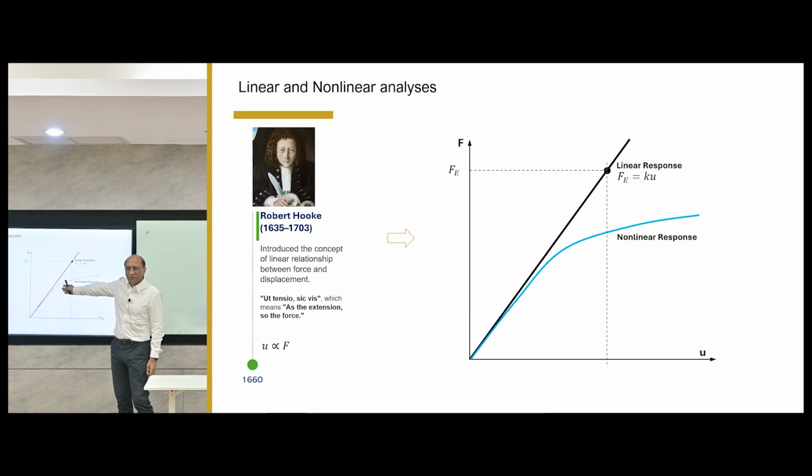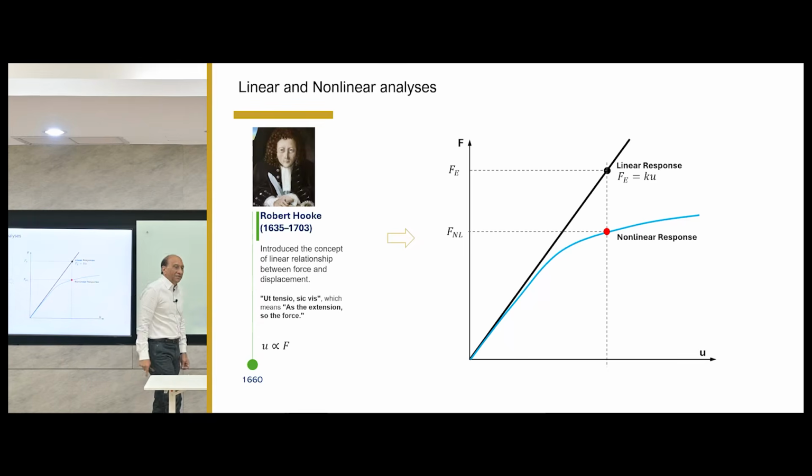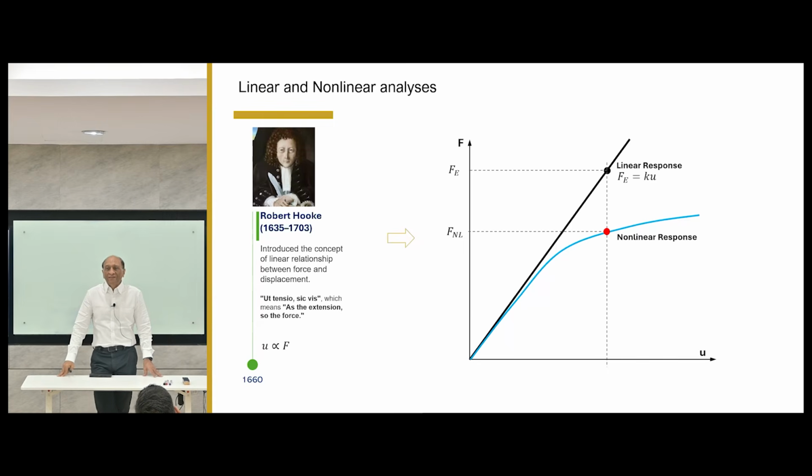Especially in earthquakes, the damage was quite obvious, right? So they found that, okay, nonlinear: for a given displacement, because displacement is the primary variable, you remember. Force is calculated from displacement, velocity, acceleration, or displacement based. So for a given displacement, we have the nonlinear force here and the linear force over there. It's quite clear that the linear equation is highly overestimating the force the structure can take. The structure cannot take that much force at that displacement. It has already broken down, already been damaged.